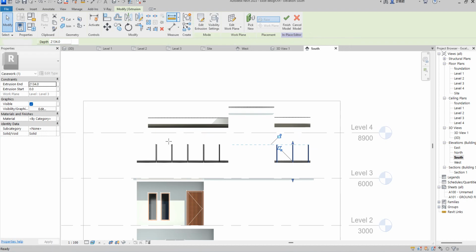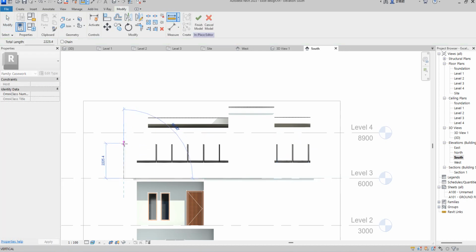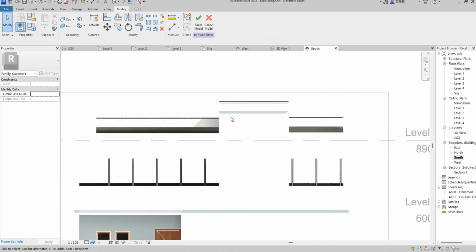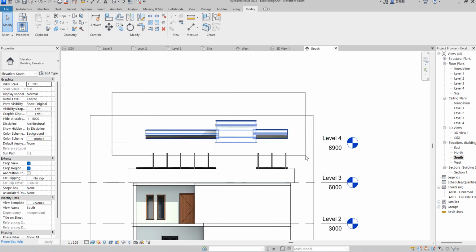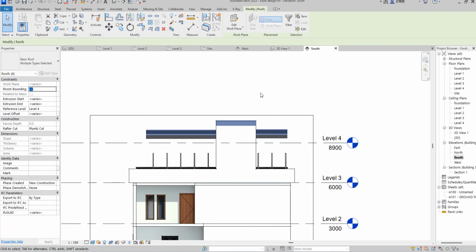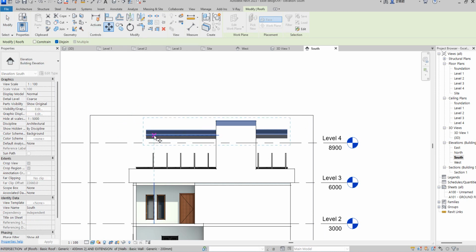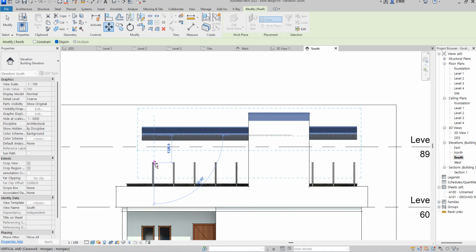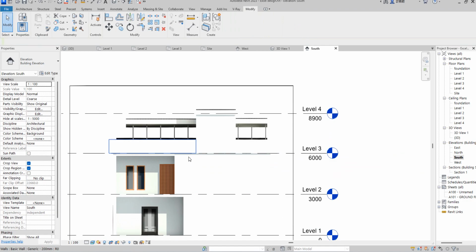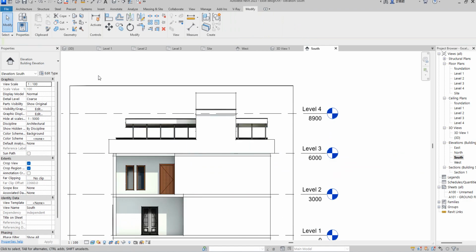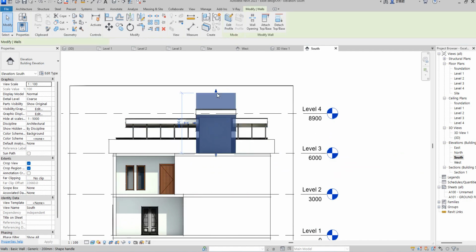So what is the height that we have? Just use a temporary height to indicate that. So I will use 2.2, that is fine. Only this one will be 2.3. So you click finish, then you select this base, then you adjust it down. You can move it completely from here, and start it down. Good. So I think with that height it's okay to be reckoned with.